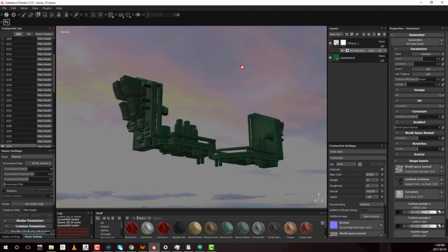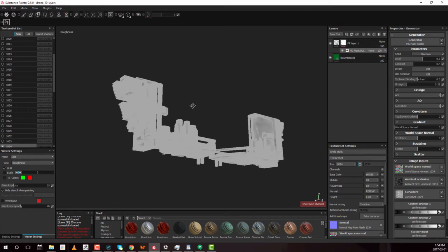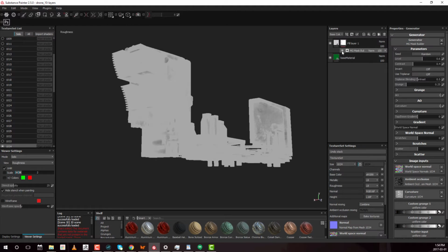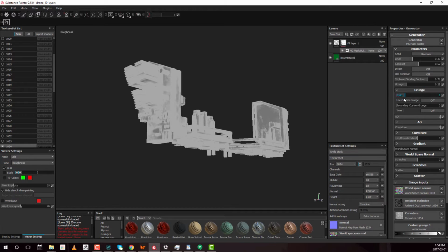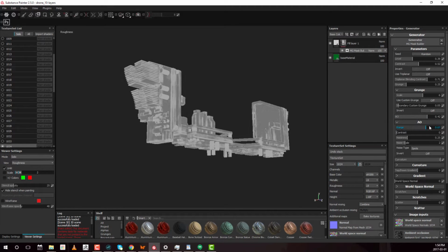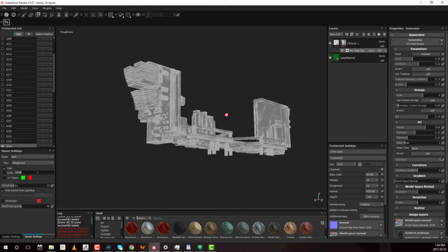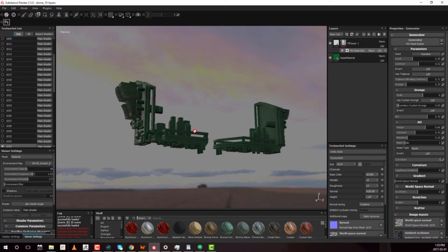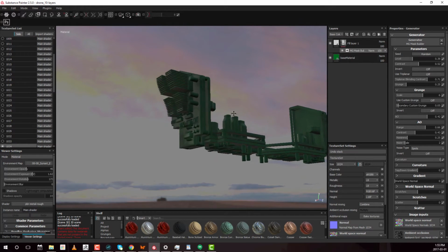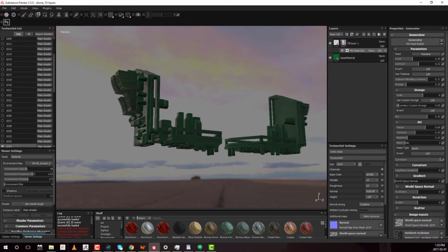And also, if I press C until I get to roughness, you'll see that it is in fact working. If I turn it off here, now you see perfect gray. Now you see some values. So if I change some of these properties, like levels and contrast, things like that, and then maybe add some grunge, I'm going to expand this grunge and then add some more scale to it, and maybe some secondary, and then I can turn AO on or off. So anyways, I can basically dial in the exact values that I want for this roughness value. If I want to see how it actually looks overall, I'm going to press M again, and now I get something like this. So this is nice because now I have a material for this base that's got some level of roughness, and this looks okay for now. I can refine it later, but for now, it's good.